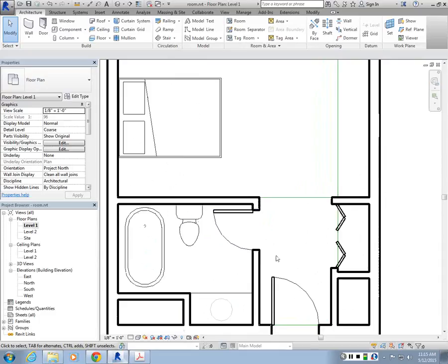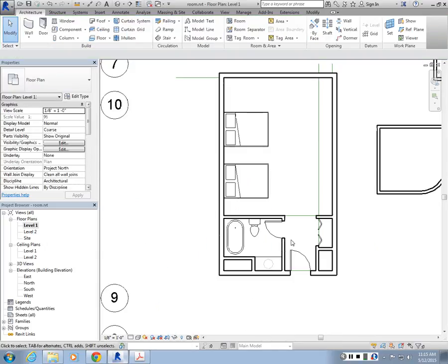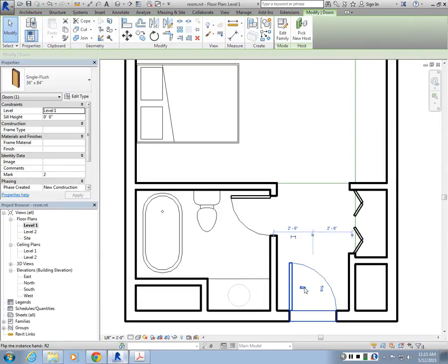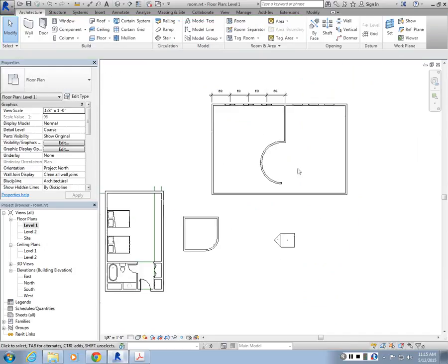Same arrow is placed twice for the doors, because we can switch the direction we want to open the doors, as well as which side of the wall we want to open them to. Technically, we draw the doors opening towards the wall, so don't draw them like this, because you will get trapped in the corner. But in this case, it could open this way, depends on what you want to place here, right? So it could also open towards this direction, if there's something here. But I chose to do it this way because there will be a counter or something else there. Okay.